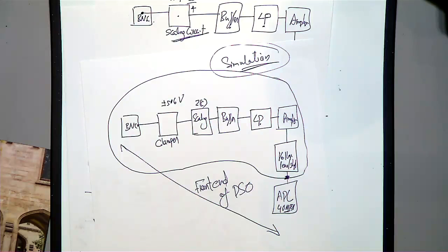Having said that, before the ADC, the voltage level shifter should come. The level shifter you can't shift anywhere; it should be before the ADC. And the low pass filter also should be before the voltage level shifter, because you can't connect the low pass filter anywhere else. Otherwise, with the buffer and amplifier you have a little bit of flexibility, you can tune it. And then I can show you two implementations. Anyway, good question. So I can show you some examples.